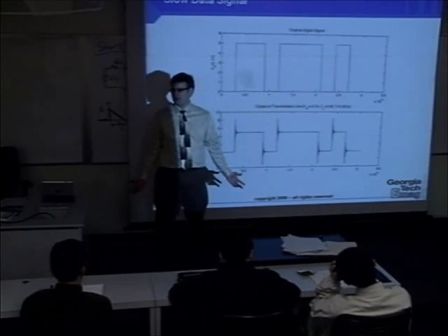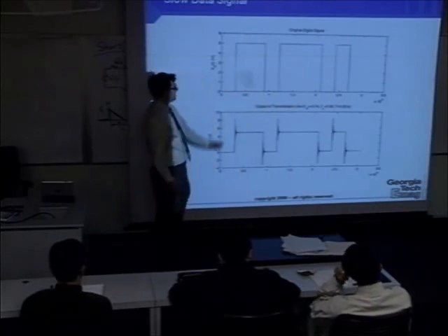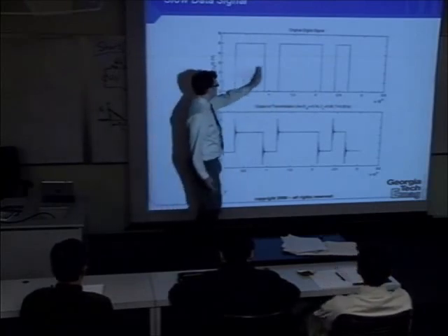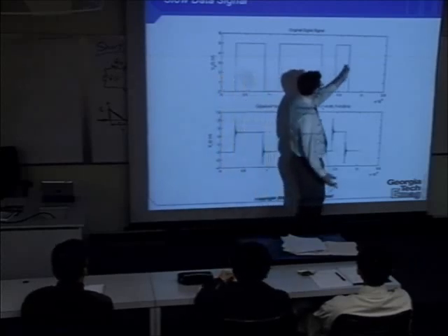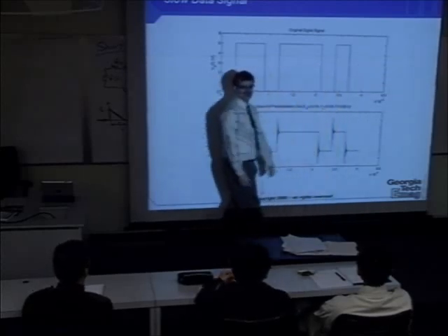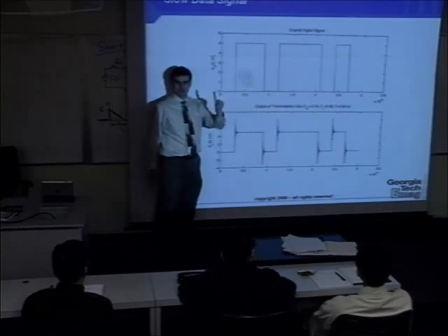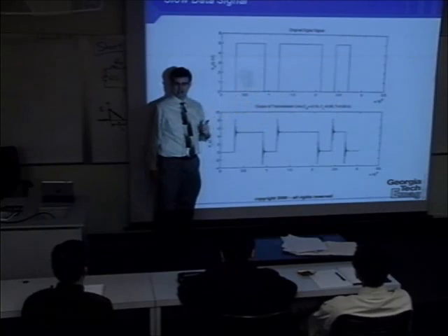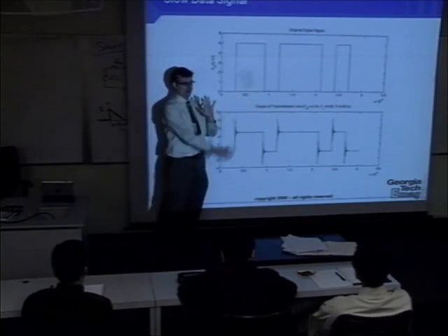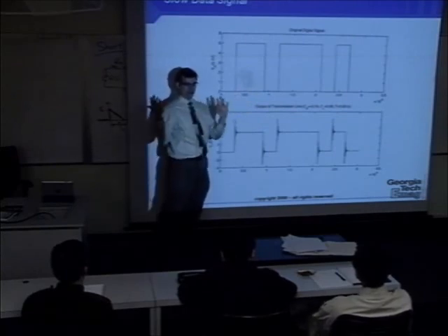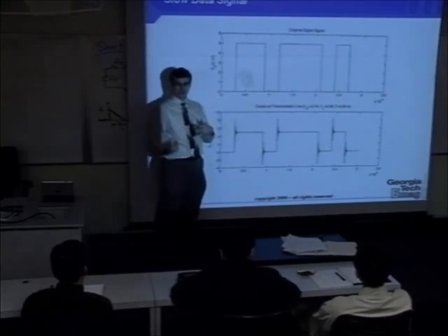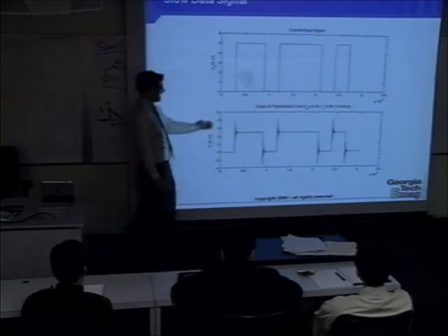Not exactly a barn burner by today's standards, but I've got a 01101110100 coming through that line. How do I use transmission line theory to calculate the effects of these short pulses? Well, I take my reflection analysis, I trace out the impulse response like I did in the previous graph, and then I convolve them. Or I actually take the Fourier transforms and multiply them together and then inverse Fourier transform them. And this is what happens.